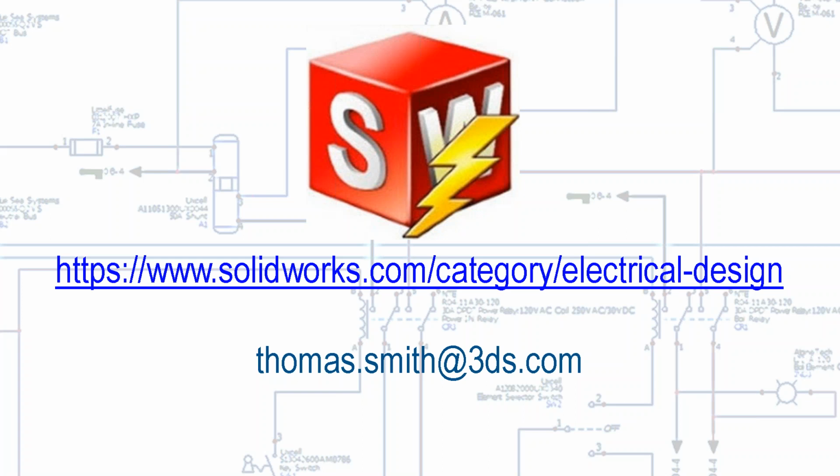Does this link to SolidWorks to route harnesses? Yes. So we have an add-in into SolidWorks Electrical 3D, and essentially it allows SolidWorks Mechanical to communicate into that SQL database so we can share project information between the two organizations. As we populate the schematics, those components can become available to the mechanical guys who can connect those up. Once they're associated, all that wire connection to-from information is brought over, so that we can route accordingly.